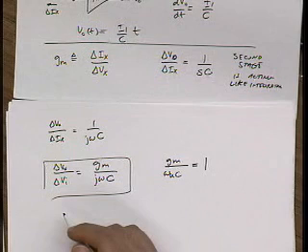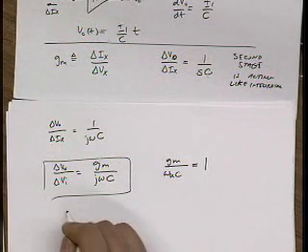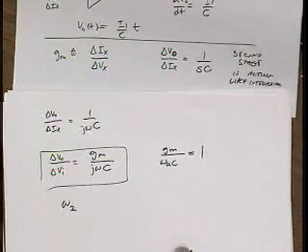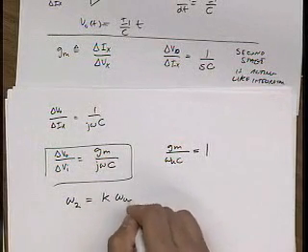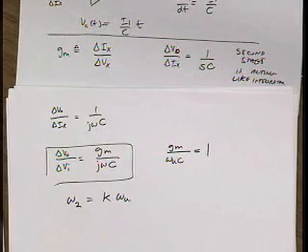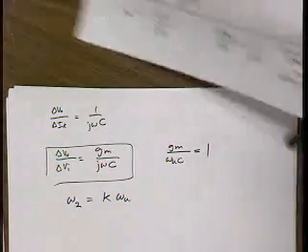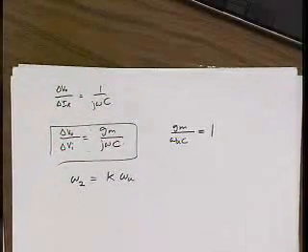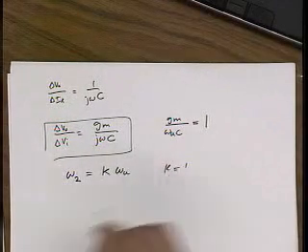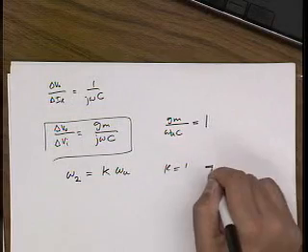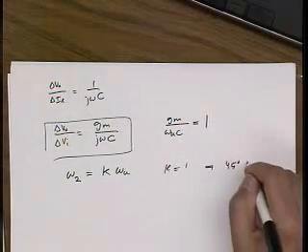And so what I can do is say that the second pole in my system is some factor k times unity gain frequency. Earlier we thought maybe k equal to 3.3 is a good choice. Let's just take it equal to 1 for simplicity. That gives us a 45-degree phase margin.